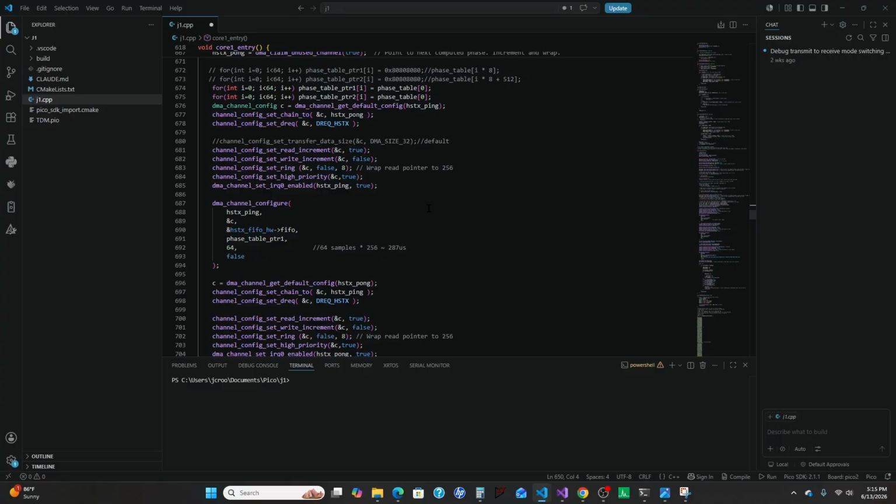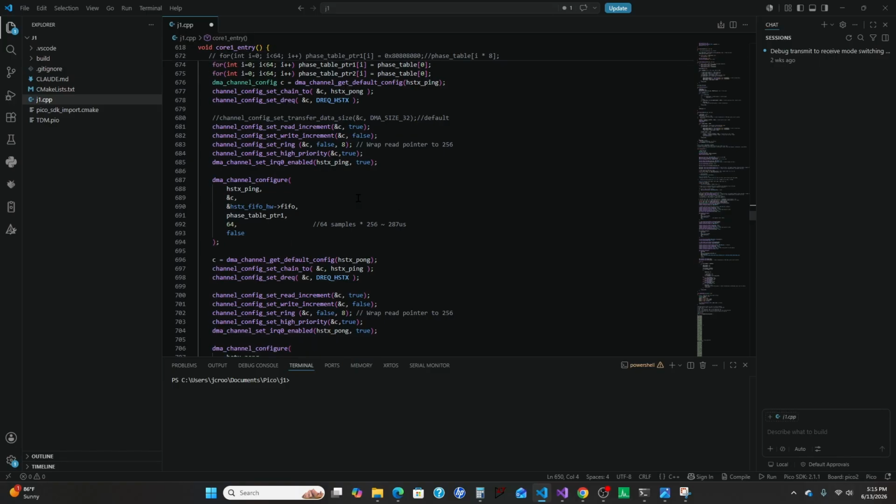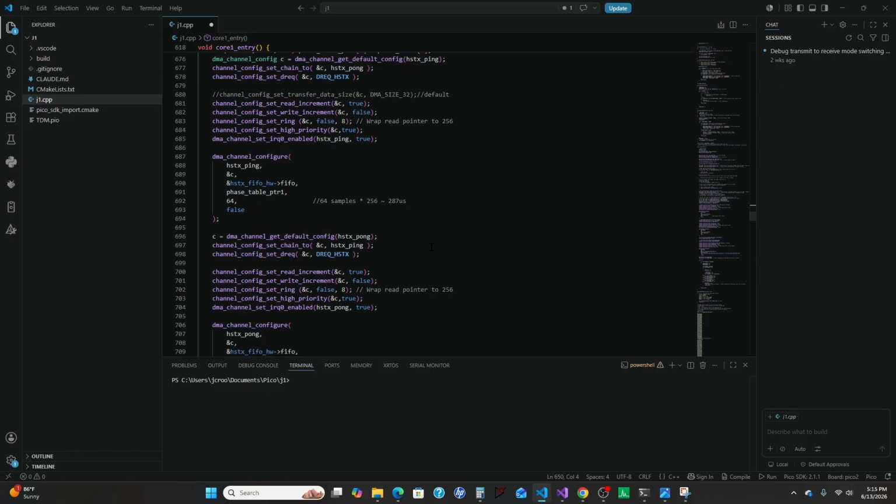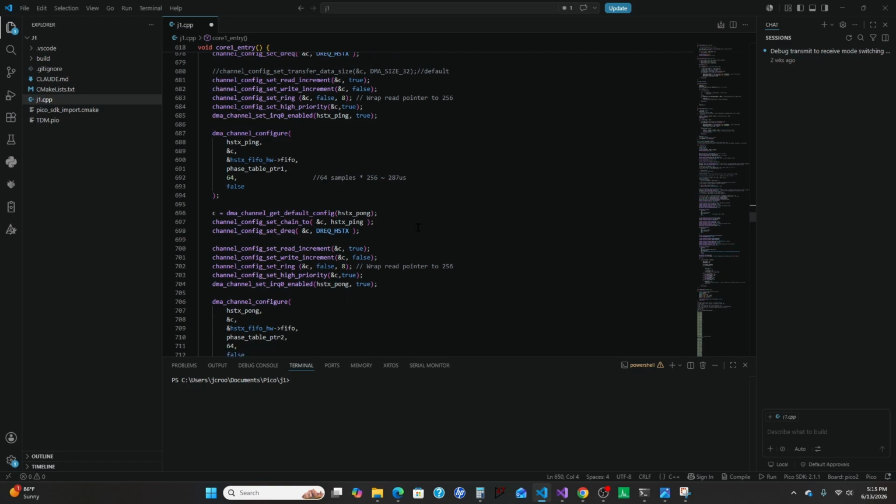There's more documentation if you look through the RP2350 manual. This will probably all make more sense. We're configuring it for 64 samples, and then to automatically wrap on those 64 samples using the DMA and the fast writes. That's plenty large enough for us.